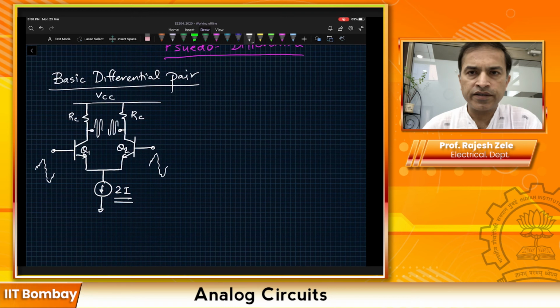So when you look at the differential signal, you will get a really large desired signal being amplified, something like that. The time scale is not correct, but I think you get the point. This is your VI plus, this is VI minus, so then you would get an inversion here. This would be VO plus and this would be VO minus. This current source which we introduced is also affectionately called a tail current source, and all of us know by now how to implement these current sources. That's what we learned in the previous lecture.